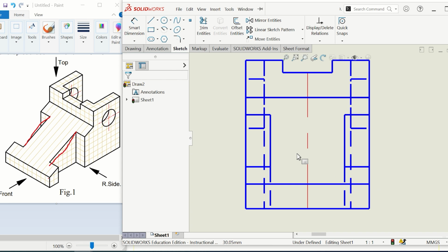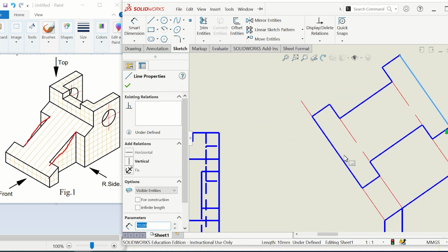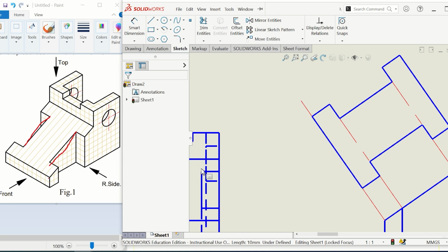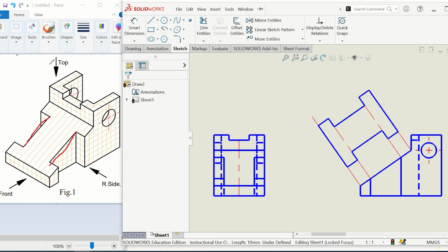And if you see that eye shape in the front, it is distorted. It is shorter. This dimension from this line to this line is shorter than the actual dimension, which is the distance from this line to this line. In the front, the eye shape appears, but it is distorted. It's shorter. How does it appear from the top? Exactly like it appears from the front. If this is a 45-degree bend, is it an incline? In any case, it's going to look shorter in the top, wherever the angle is. Whatever the inclination angle is, it's going to appear distorted in the top and in the front because it is